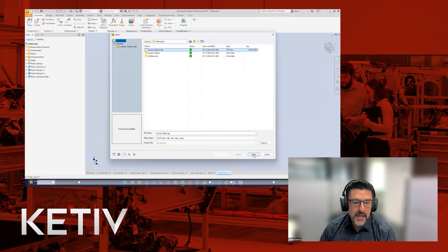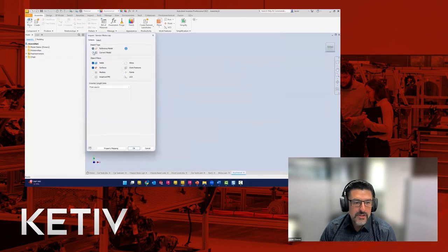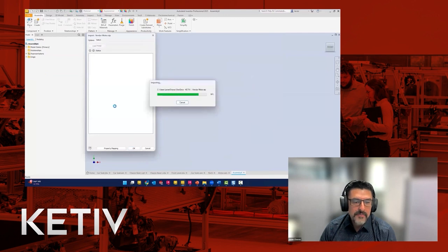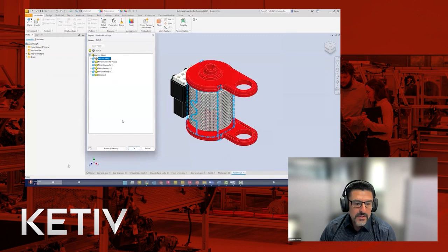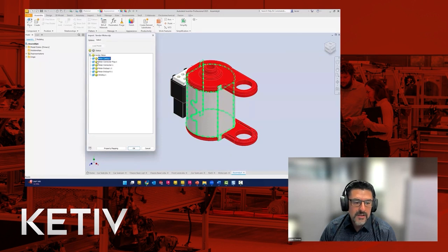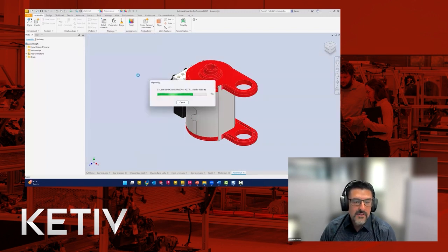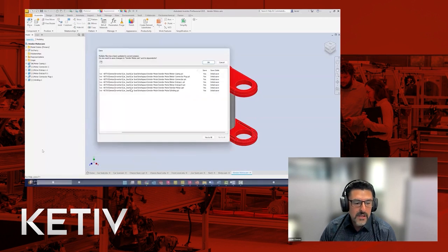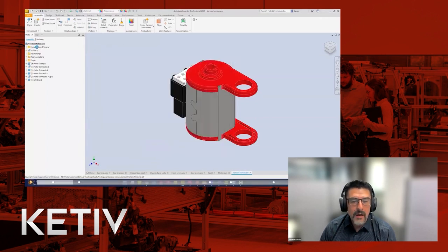So as we bring it in and open it up, it goes through a conversion process. You have the choice of linking it or converting it. We want to convert it so that we can have some choices. And you could get a preview. And in the preview, as you go through this preview process, you could decide and just see, well, what things are a part of this file. It looks like it's an assembly, and I see motor casings there. I see some internal components and things that we already know we don't want. That internal thing that you see there, I don't know what that is. It says winding, but we're never going to see it. So you could turn it off here. I'm going to leave it in so that I can show you more ways as we import it into our environment that we can simplify it.